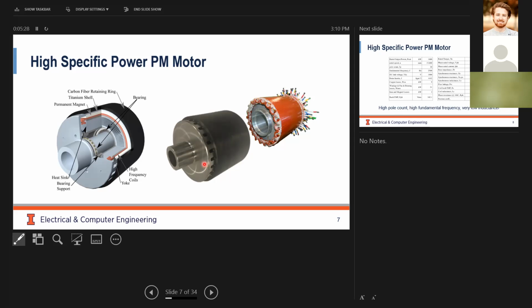So this motor is an outer rotor motor with self-driven fans as the cooling strategy. The permanent magnets are Halbach arrays, so we can have a very strong magnetic field. And then we have air gap windings, so that the teeth are removed and a large portion of the iron losses can be removed as well.